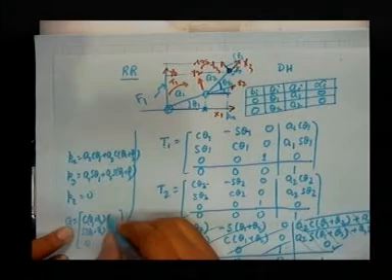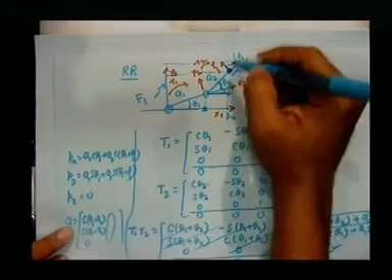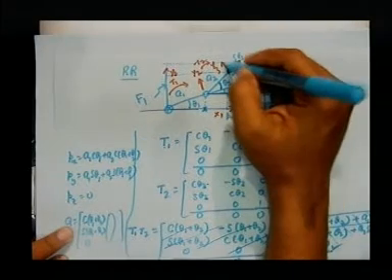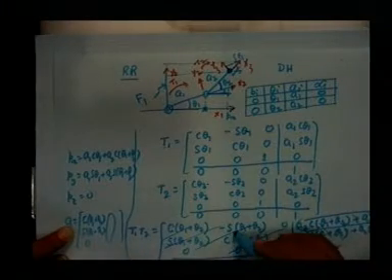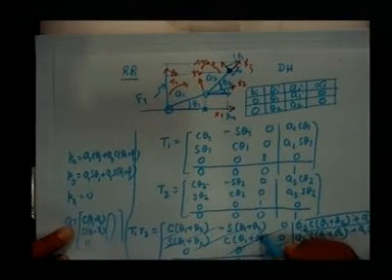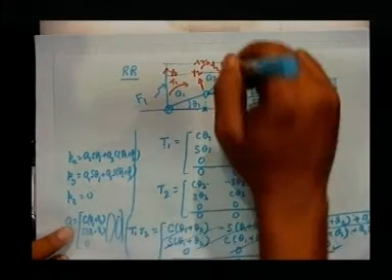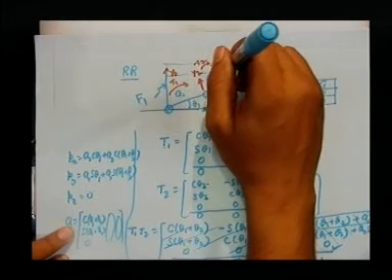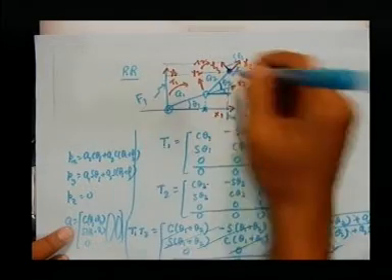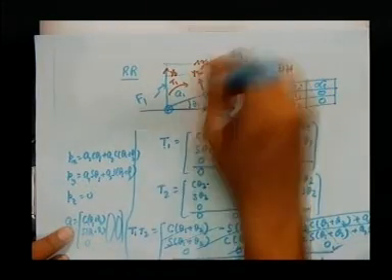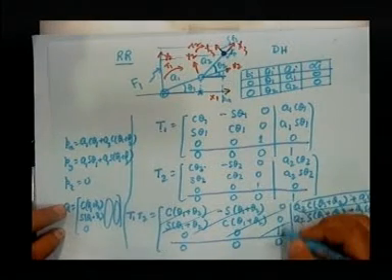Now, if you want to write the second column, this will be the components of y3, the unit vector along y3, in x1, y1, and it can be very easily checked that this will come out to be minus sin(theta 1 plus theta 2), cos(theta 1 plus theta 2), and 0. And the last one, which is the z column, vertically above the paper in the fixed frame, and these two are parallel. So, z3 is parallel to z1, so obviously it will have 0 0 1 structure.